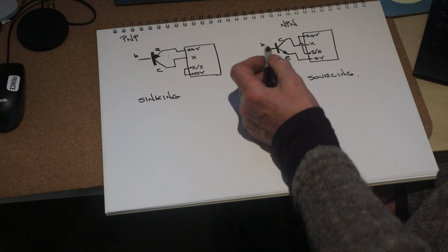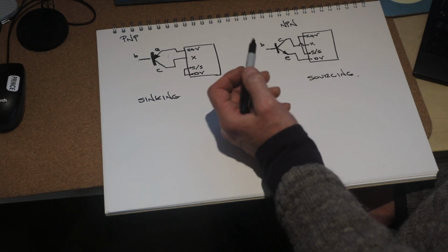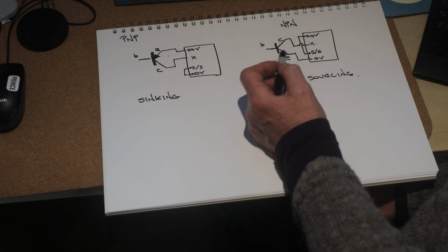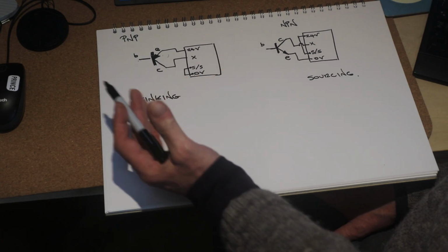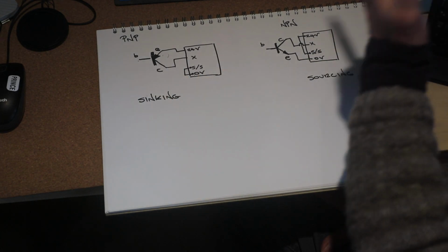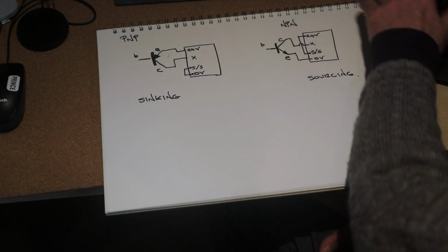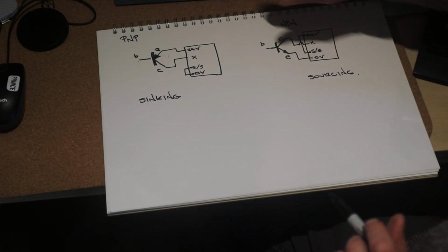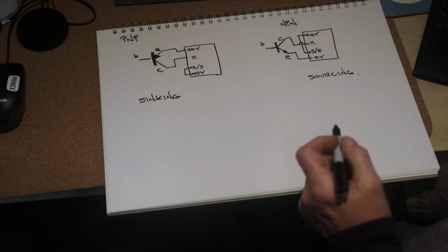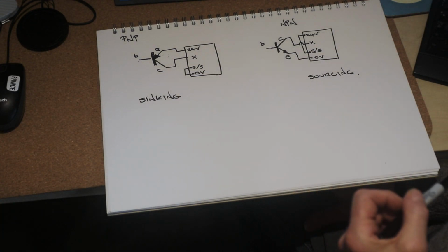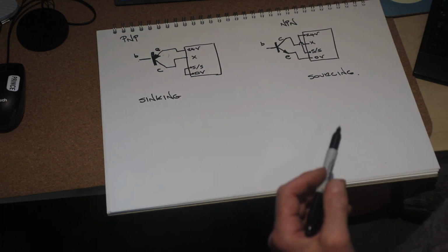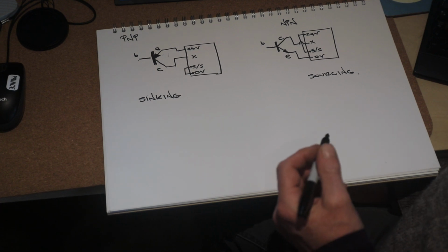That's about how the transistors work. The sensor will be different. So some sensors, whether optical, temperature sensors or pressure sensors, might be more suited to using an NPN style transistor. And some sensors might be more suited to using a PNP type transistor.